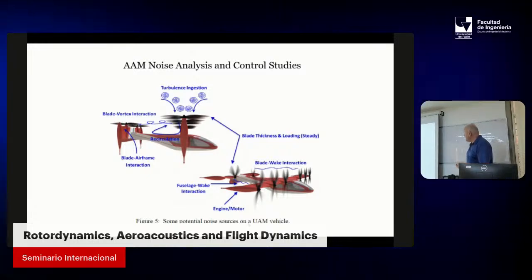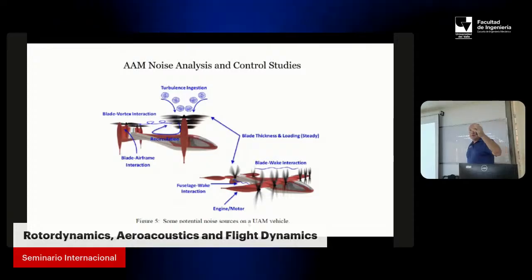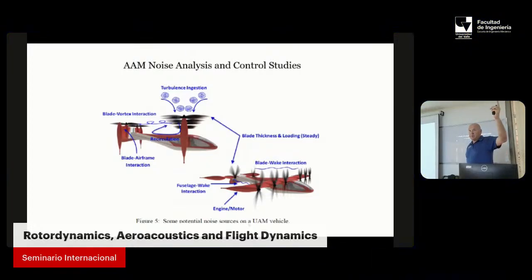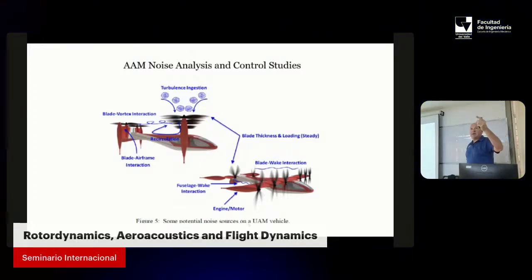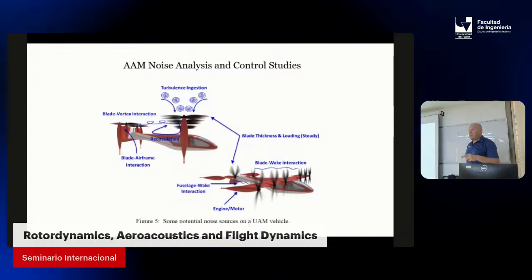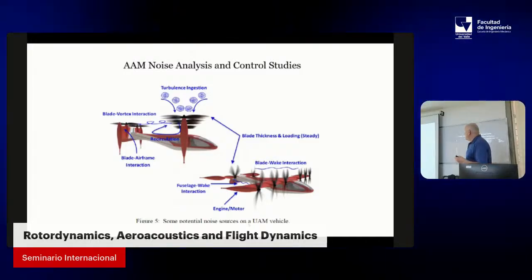when you have a single rotor, you have a lot of loading, and it's a very high Mach number. Usually it's almost supersonic tips, it's transonic. So it's very high tip Mach numbers, steady loading. That produces a huge tone, and that's why helicopters are so loud, because that's a lot of noise.